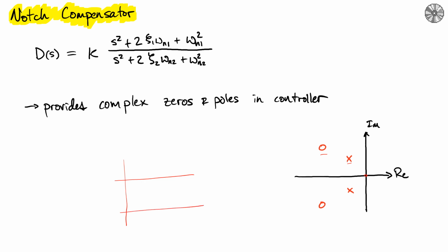So if you have 1 over a quadratic, you have 2 complex poles, then you're going to get a negative phase. And the breaking point of that phase is actually motivated around this omega n value. And the same thing, so with a pole, you would have a notch, and then it would go down. And so this notch, the placement of that notch, is again where that frequency value is. So changing that frequency value here or here shifts where they are. And again, that omega n, remember, that's essentially the distance from the origin out to either of those.